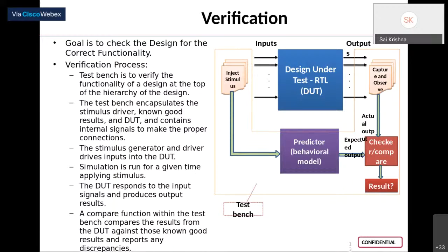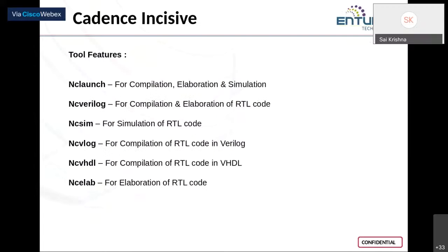So that basically sums up your front end part. Your chip architecture, the top level, and then your block level architecture, and based on the specifications given for every block, you write down an RTL code in either data flow, structural or behavioral model. After that, once you write your RTL code, you also write its test bench, making your RTL code your DUT, design under test. You force the values from your test bench onto the main logic and compare the captured values with the predicted value.